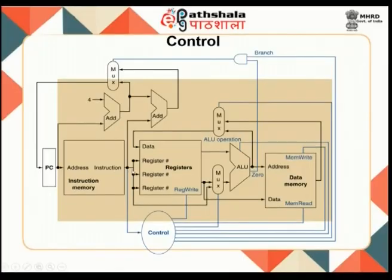This is just to give you a feel of what the various control signals are, and you can't just ignore the control signals. So, when the instruction is decoded, that instruction information is given to the control unit, and depending on what type of instruction it is, the various control signals are generated. These control signals will be applied at the appropriate times in order to control the flow of instruction in the instruction unit.